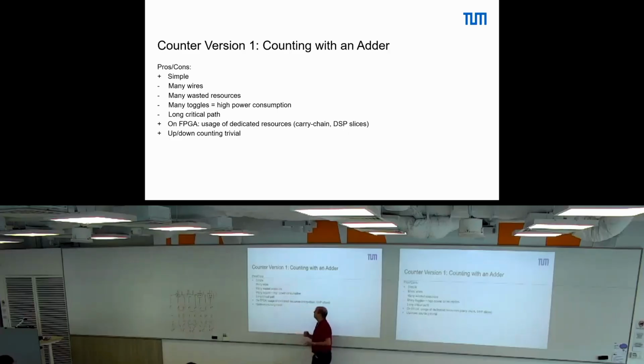Wasting resources in terms of we need more wires than we actually need. So just for instance, if you look into the ripple carry adder, and you always want to add only 1, then for all besides the last one, you could actually fix 1 input to 0, which just removes this. There's an AND gate behind that somewhere. The AND gate is always 0. We can remove the AND gate. If we have this gate inside, an additional gate may cause, for instance, this.